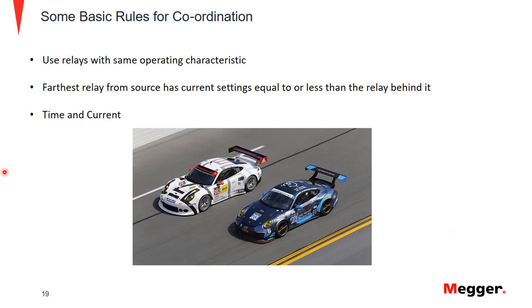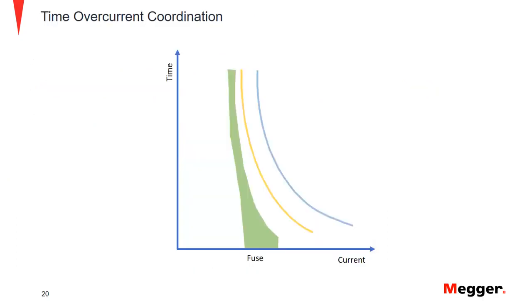So let's go next. All right, so in the coordination example, we're going to line out a couple of examples here. The first one is we'll actually throw in a fuse. We actually have a fuse damage curve here. We also have our normal feeder that we had earlier in our main. Still, again, inverse time overcurrent. So we're still talking about the same current, same TCC. We're still talking about the same style of inverse curve.